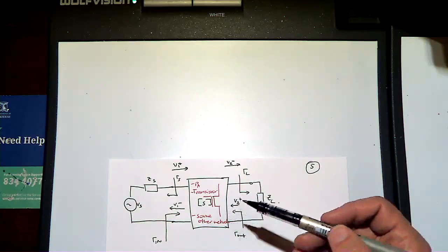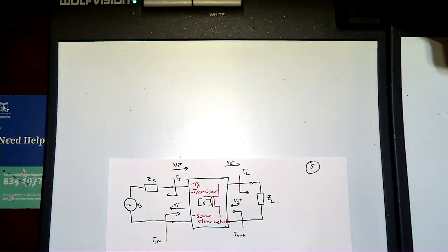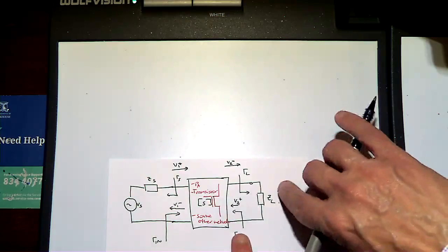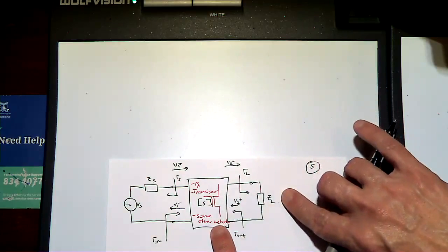Because if you want to use it instead of big circuits, then we need to figure out whether we need a voltage buffer or something connected to a small impedance later, or we need to match impedance. Sure. So generally, when you're trying to feed a network, you want its input impedance to be conjugately matched, so that you can get maximum power into this network. And also, in most cases, you want the output impedance to be matched to the load.